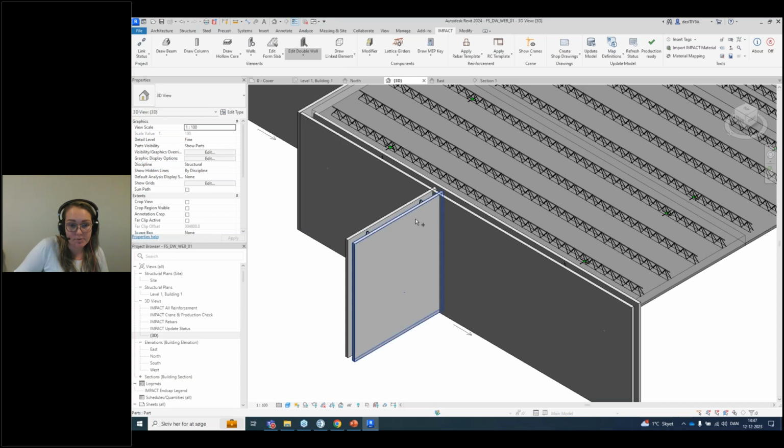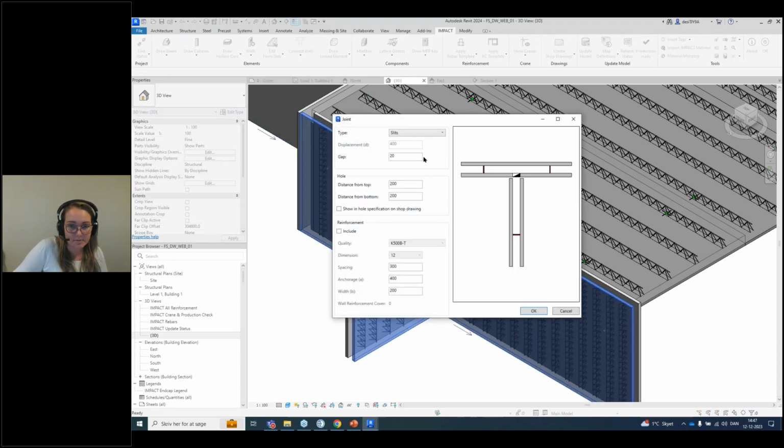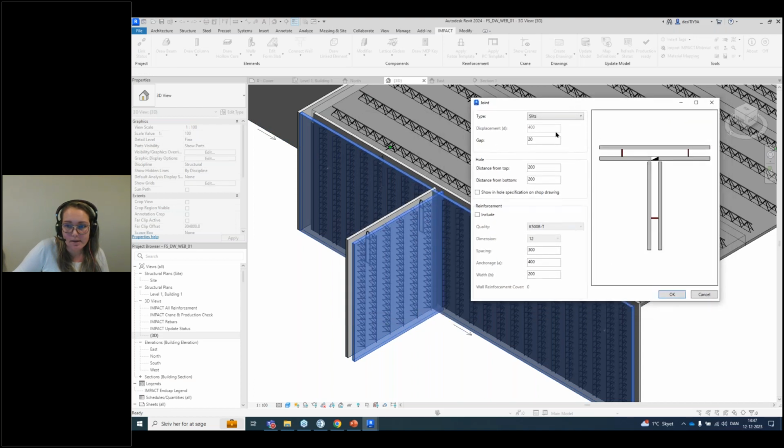So I say connect wall and I select those two walls. You can just select a single panel. And here I can do some slits, I can do an open hole automatically, or I can go to left or right side. Let's do the right side so we can see it here from this view.